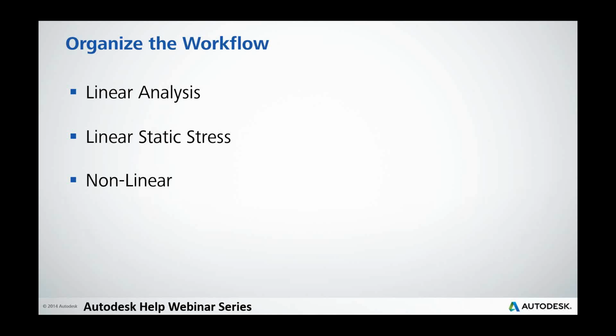Based on the outcome of that, we can determine whether or not we need to do a nonlinear analysis. And a lot of the time we get people trying to do a nonlinear analysis right off the bat. That's usually the most challenging one, and it often takes the most time to do an analysis. So we try to steer people back to doing these linear analyses first in order to save time and just begin to get an answer.